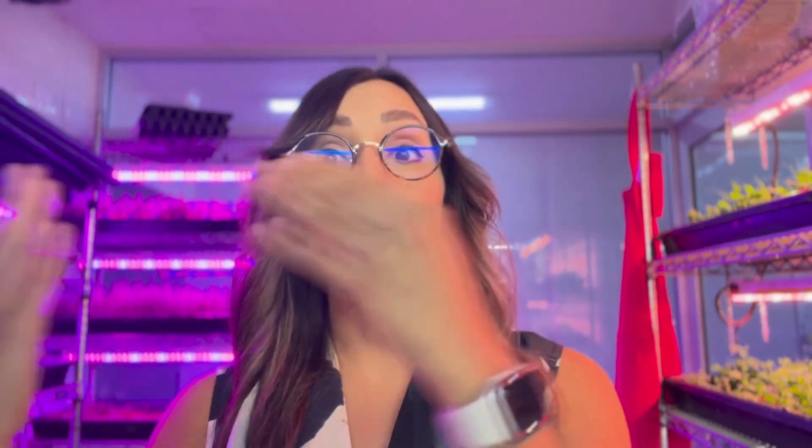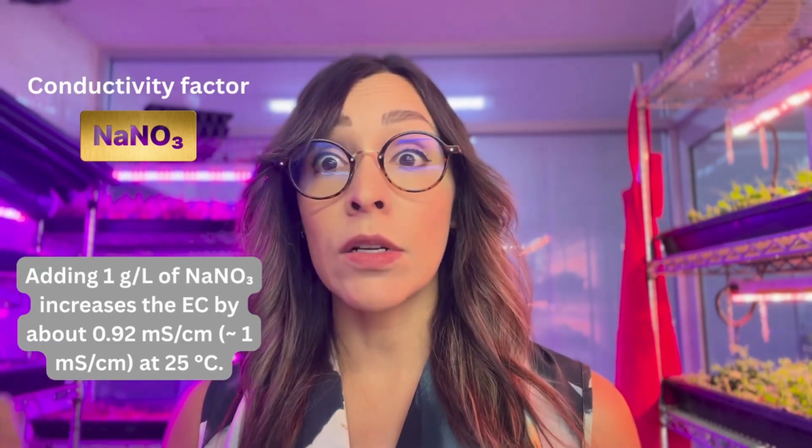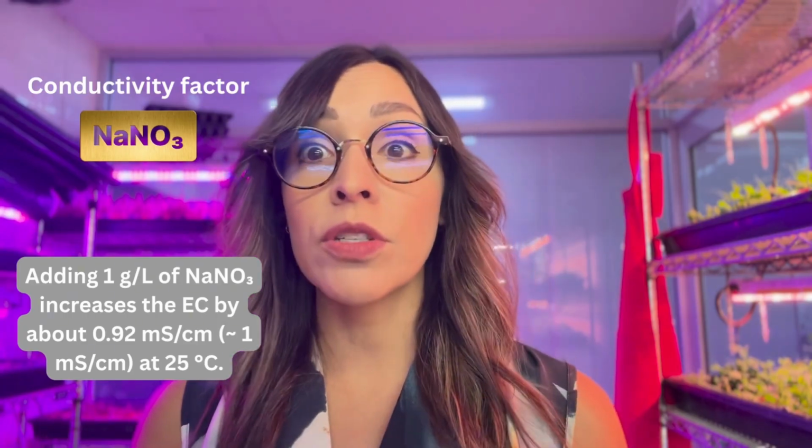So sodium nitrate will have a specific conductivity factor that is going to increase our EC. That's why it's not that simple to calculate the increase in EC, but in this case, we need to look for the conductivity factor for this specific compound, which is sodium nitrate. The electrical conductivity can be affected by temperature, so I'm going to use the standard temperature of 25 degrees Celsius to provide information. For sodium nitrate, the conductivity factor would be an increase of 1 microsiemens per centimeter when we add 1 gram per liter of sodium nitrate. So this is specific for sodium nitrate.